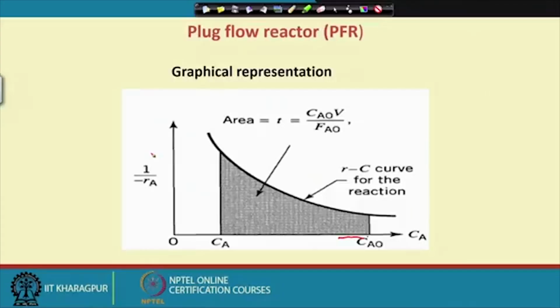So, this kind of correlation is valid when there is a product inhibition in the system. This is product inhibition, am I right? So, in case of product inhibition, our choice is the plug flow reactor. Now, of course, since I told you the plug flow reactor is very difficult to operate, am I right? Now, how is it possible? The question comes: is it possible to replace the plug flow reactor by CSTR? The answer is yes. How can it be done?